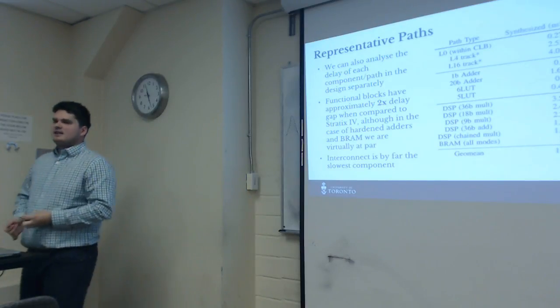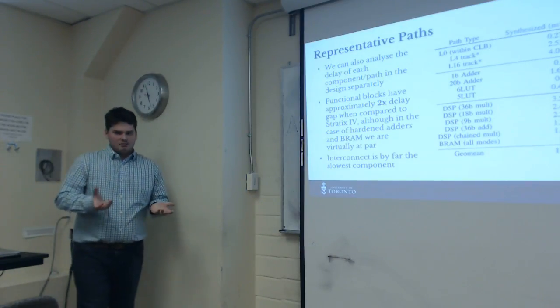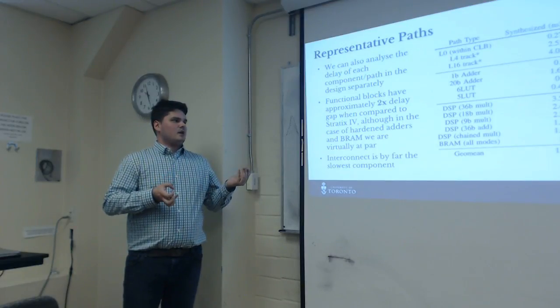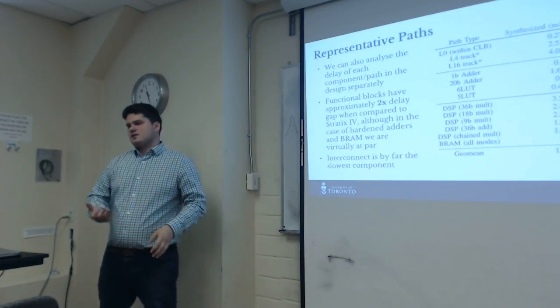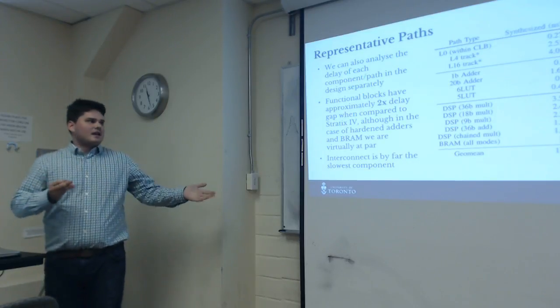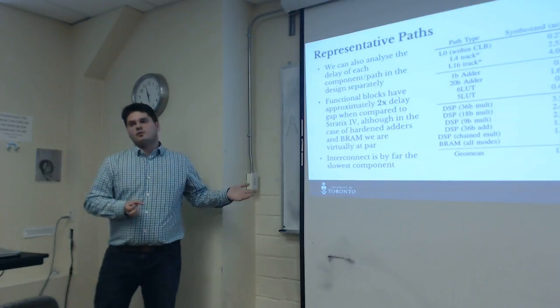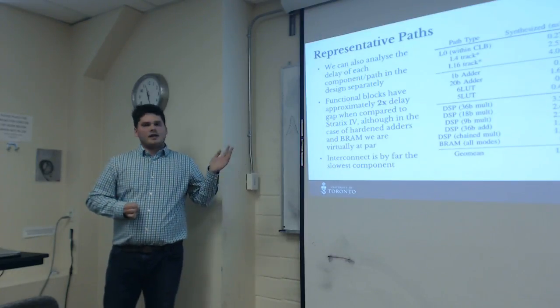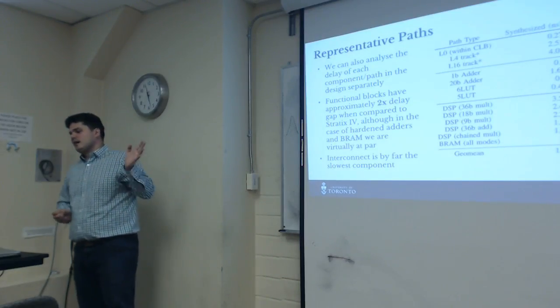It's very likely that they're pulling out all of the stops on TSMC's 40 nanometer node to get high performance transistors, lots of leakage, to get these things as fast as possible, and we're not doing that. We're just using a standard library. So that's probably why we're getting so much less performance. That's something we have to analyze in the future.